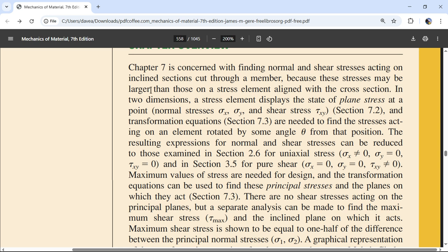So we kind of talked about that, and that's the case if I have a steel bar. Just imagine a steel bar, and I'm pulling on it in either direction. I'm tensioning it till failure, and it's a 1-inch cross section, so it's a fairly thick steel bar. I always bring up this one because it's 58,000 pounds. I can put 58,000 pounds on that 1-inch square bar.